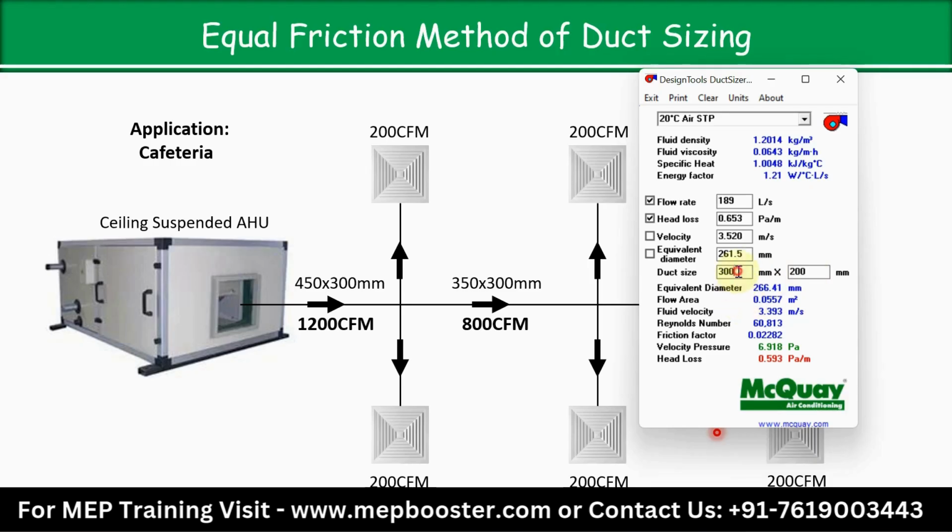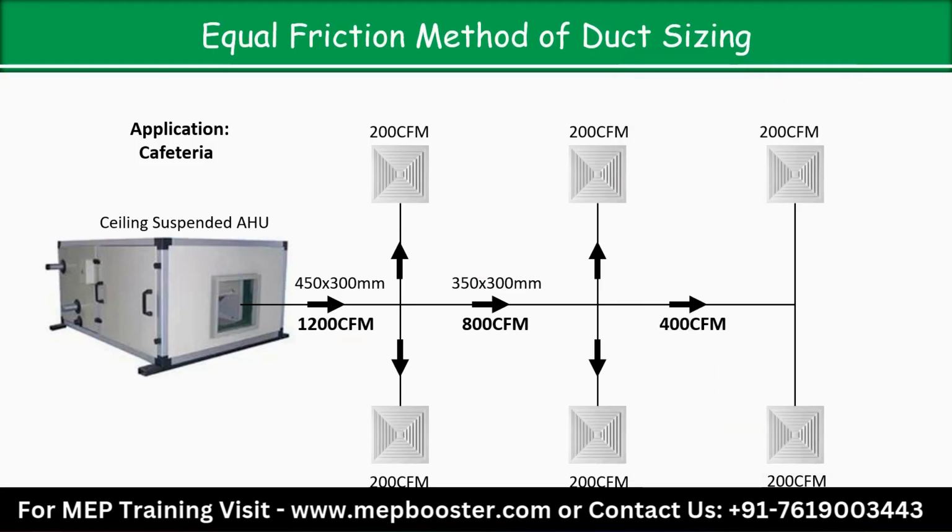So now you have to reduce the height of the main duct to increase the width. I am taking 250. If I take this height 250, the width we are getting is also 250 only. Okay, is it clear? So you can select a 250 by 250 mm duct size from here.